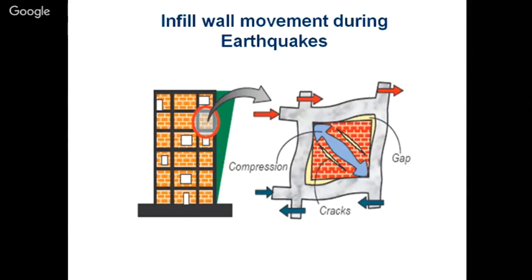But while analyzing that same structure in the computer software, we don't consider that brick infill in our analysis. The reason this matters is that if you are not considering that stiffness, but it is actually there, it is contributing to the actual movement and behavior of that particular structure. But in computer modeling and software analysis, you are not putting in the brick infill.